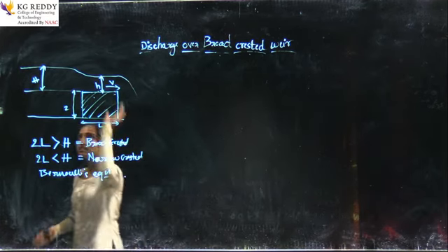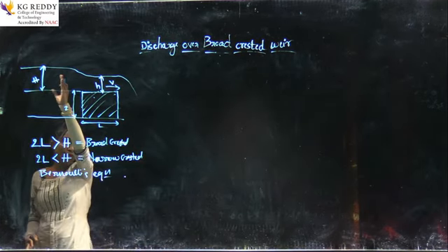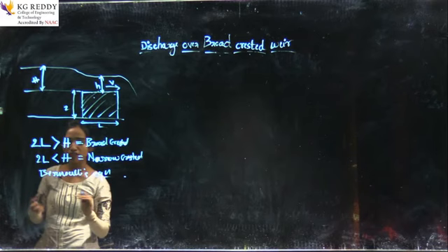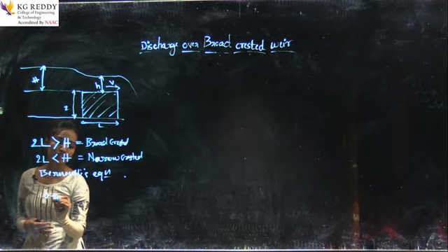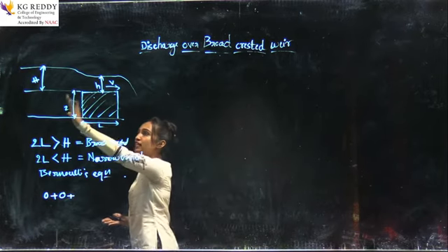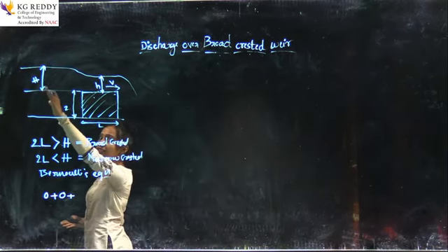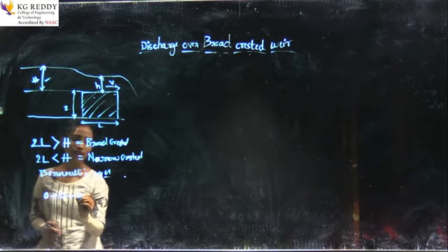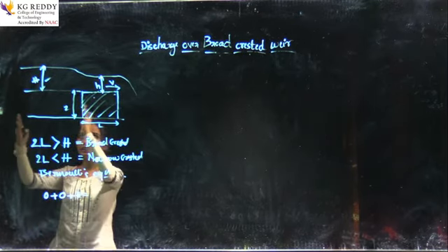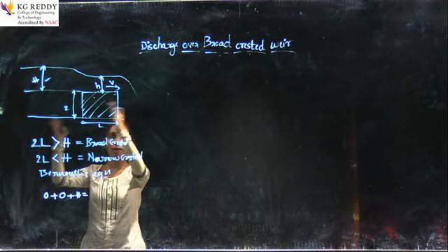Before the crest, the water is at rest, no pressure exists. So I am giving the velocity as 0 and the pressure is also 0, but head is present. Can you see the figure? Before the crest, how much is the head? Yes, head is H. So I am giving this as H. So this side is over. Now I am going to this side.